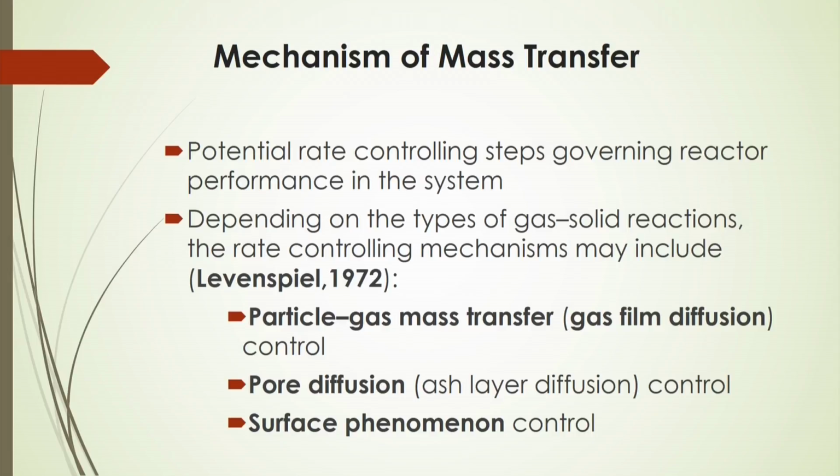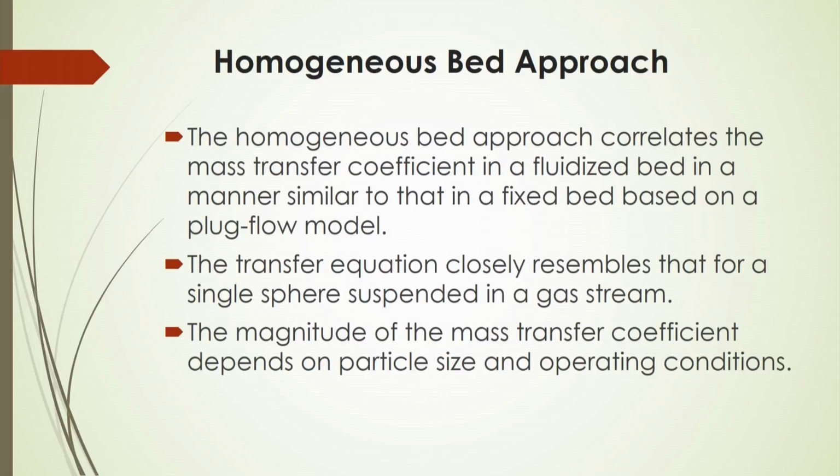And another important phenomenon for the mass transfer mechanism is called surface phenomenon control. So, surface phenomenon control, pore diffusion control, and particle-gas mass transfer, which is called gas film diffusion control, are the three mechanisms that generally govern the mass transfer inside the fluidized bed. Let us start with one by one.